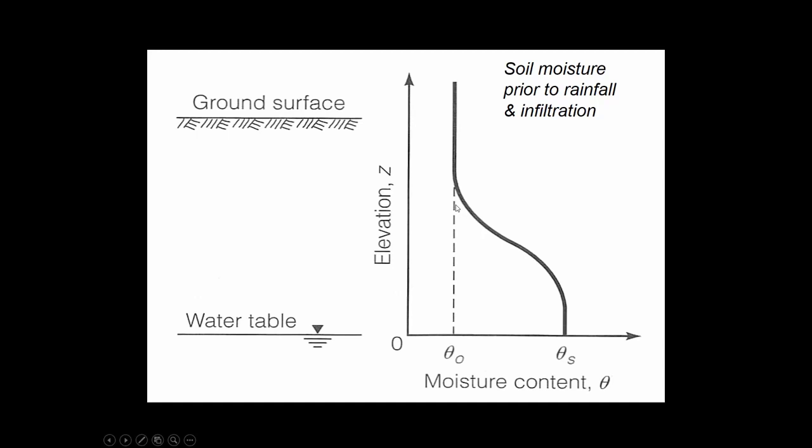There's a whole variety of void spaces in the subsurface. Remember that if you've got a mixture of sand and gravel and clay, there are going to be some paths from the surface down to the water table that have a relatively large diameter for the interconnected route to get there. There are going to be some places where there's just a series of tubes that, by coincidence or statistical anomaly, have really small diameter voids.